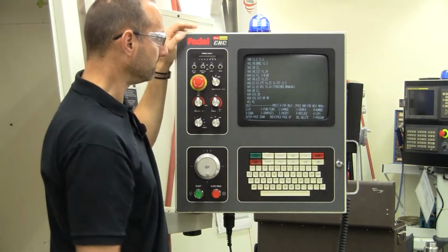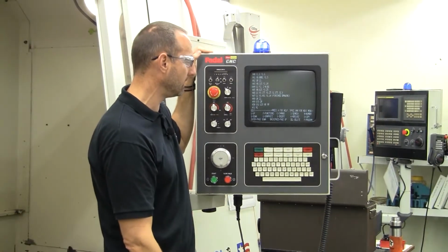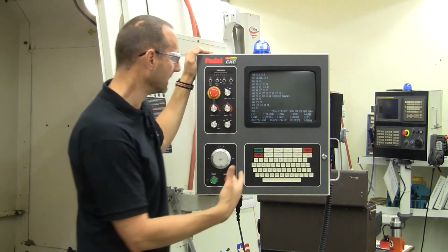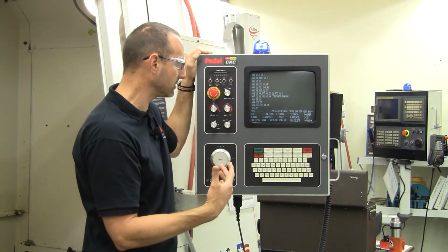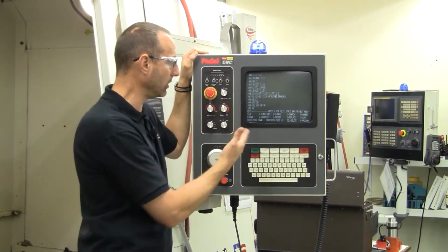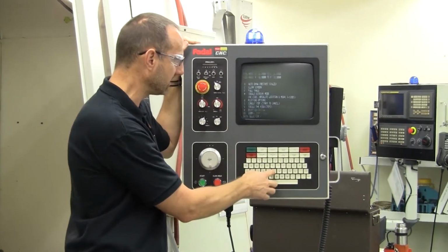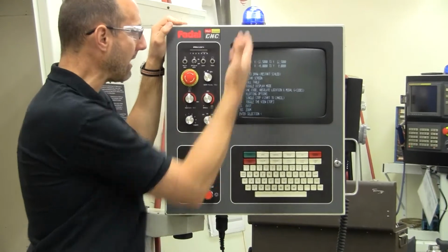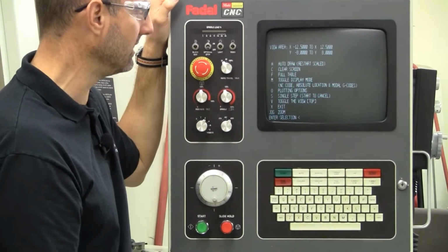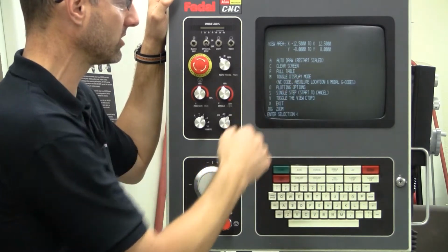Okay, that's the bulk of the editing functions, and then there's one last component in the editing function that is useful, and that is essentially graphics mode or backplotting. And this is a program verification tool. It allows me to look on the screen at the program that's loaded to give me a visual indication of what it's going to do. So to enter into that, I can press G for graphics, and then I have some options here to see what's going on. There are two options that I typically demonstrate for the students to use, and that's Auto Draw, A, and C, Clear Screen.